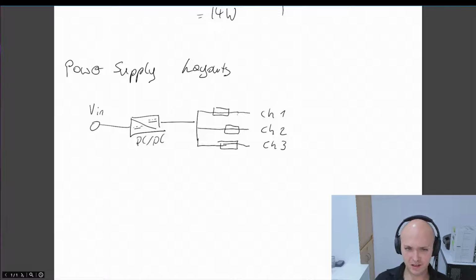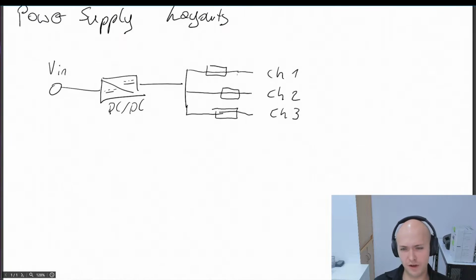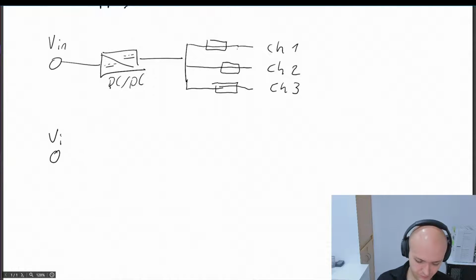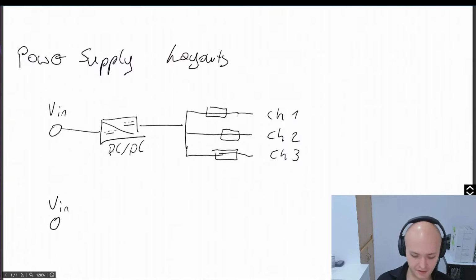And for our design goal of having an optional 5 volt LED strip support, it is not very optimal either, because we will need to add another switching power supply in the power chain, and we want to avoid that. Let's take a look at the second possibility to design such a device. So you have a single DC-DC converter.